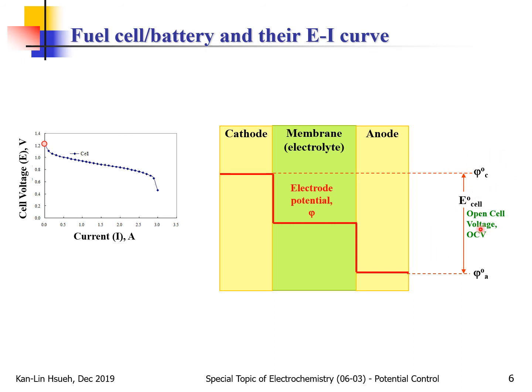The cathode potential minus the anode potential, the potential difference, we call the cell voltage, and at the condition of current equal to 0, we call that the open cell voltage. When we let the current flow through, maybe by connecting a fixed resistance, the cell voltage will be gradually reduced. So the potential profile will look like that. There will be a gradual decrease, and as the voltage goes further down or the current increases, the potential profile will look like this.